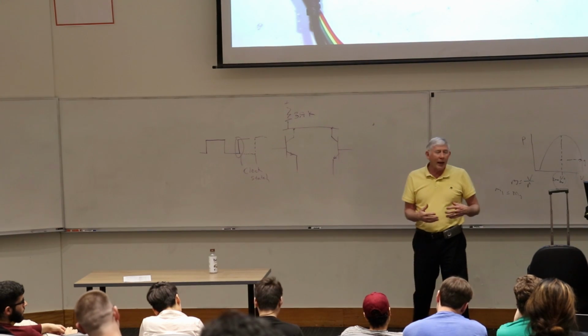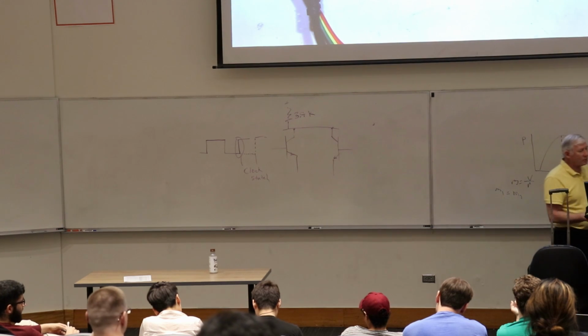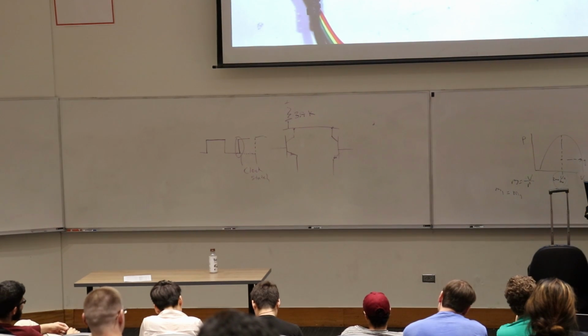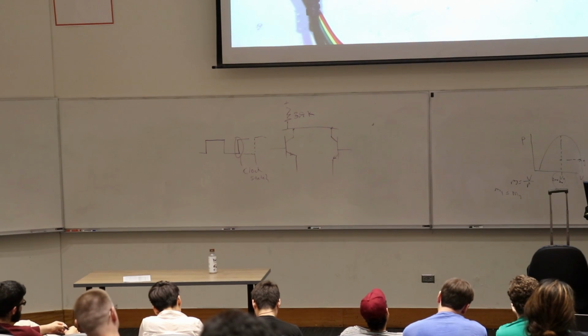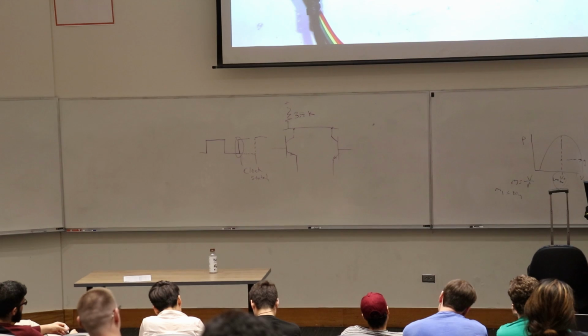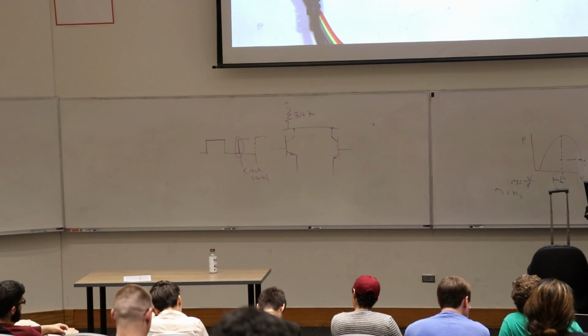So this chip will support that. Now, if your other slaves are hardwired chips like this PCF8574, then that's not going to work because they don't have that built into them. But if you're addressing, say, 4 or 5 other microprocessors, you can in fact build that into them.